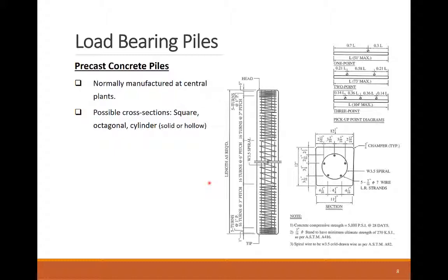Precast concrete piles overcome a lot of the timber pile constraints, but they come with their own limitations. These piles are manufactured in precast plants with standard cross sections like square, octagonal, and circular. Precast piles have great resistance to chemicals and biological agents if the right concrete mix is used with the right tight quality controls.